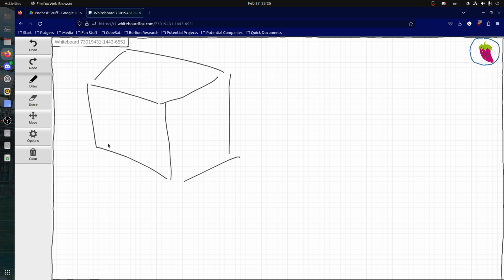So for our mission, are we using the magnet torquers to try to stabilize our CubeSat during detumble? Yes. You jumped a little ahead. I was going to mention this later, but that's fine. One thing that happens with magnet torquers is the faster you're spinning, the more you'll notice its effect.